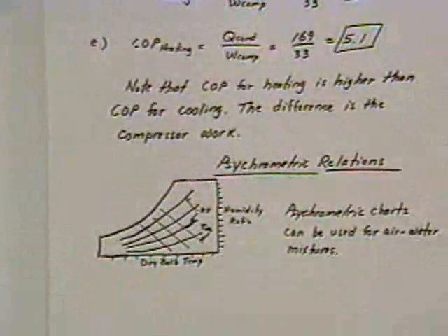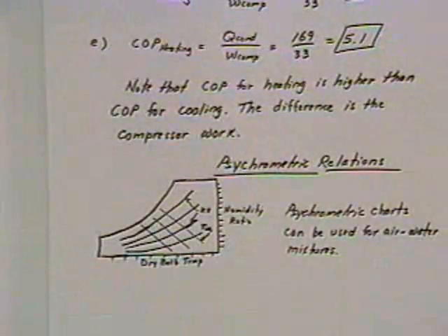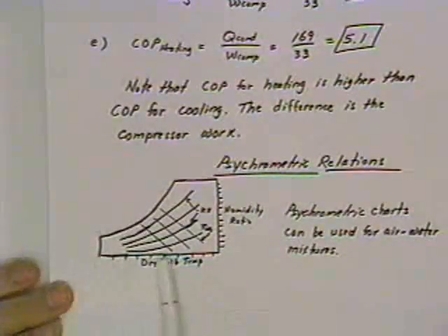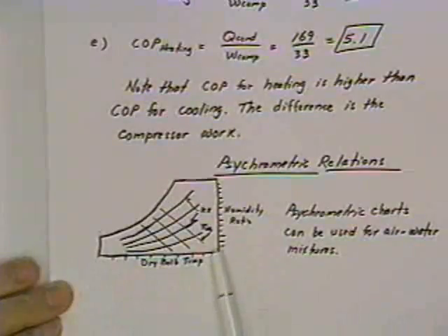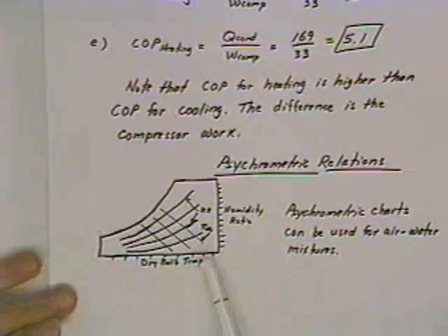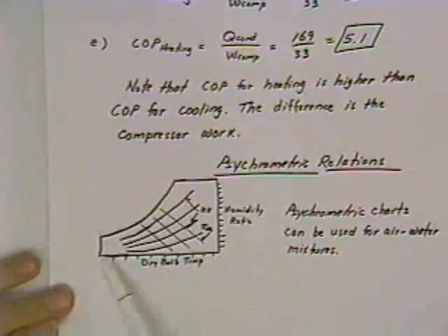But before we get into the much more complicated one in the supplied reference manual, I'd like to acquaint you with what's on it. The psychrometric chart is set up in terms of dry bulb temperature, which is just the ordinary temperature that you have outside or inside the room. So it's a hot day, it's 95 degrees outside; the weatherman always reports dry bulb temperature.